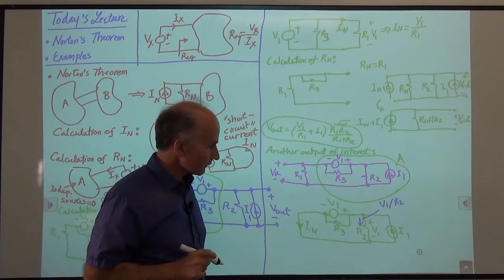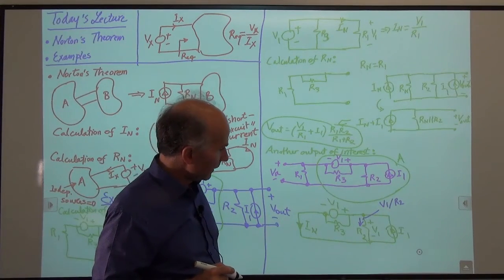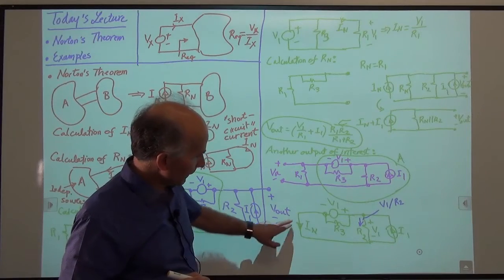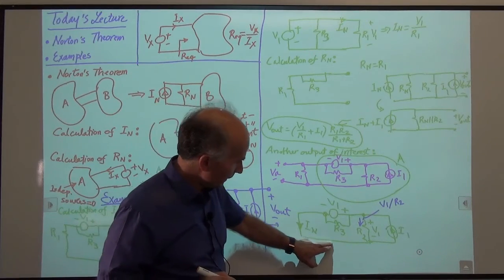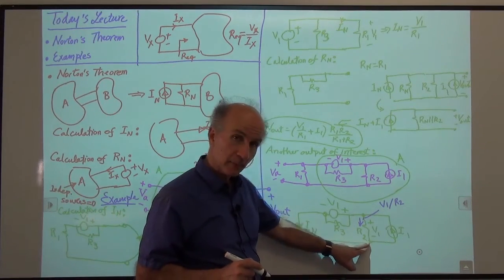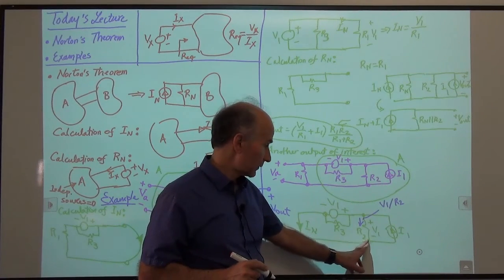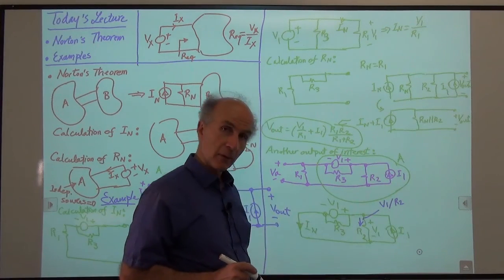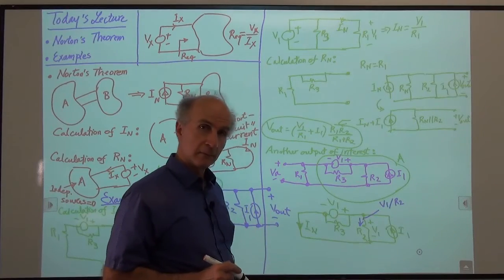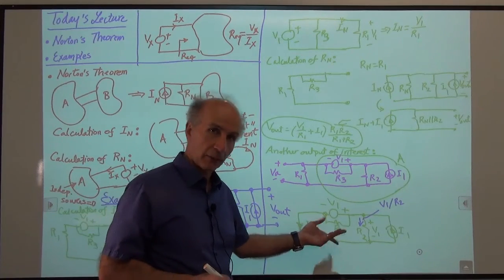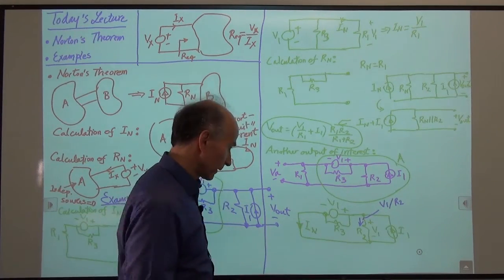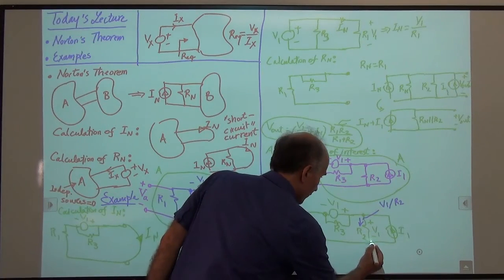Okay. All right, and then the current that flows this way is coming here and is branching out into this resistor and that resistor. So can I write a KCL here? I can write a KCL. I haven't called it ground, so I'm going to write a KCL here, right? So let's write a KCL at this node.